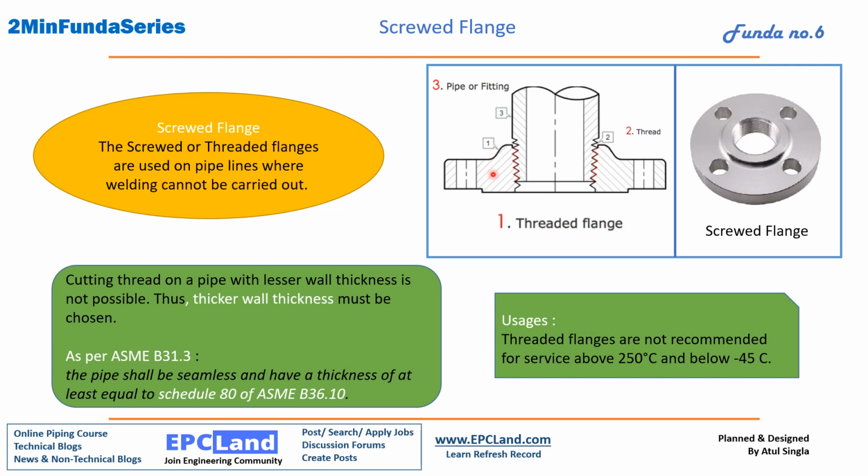If you see, this is a threaded arrangement on the pipe as well as the flange. So this way these can be threaded to each other. These are commonly used threaded screwed flanges in the chemical industry, and these types of flanges are not recommended for services above 250 degrees or below minus 45 degrees Celsius.